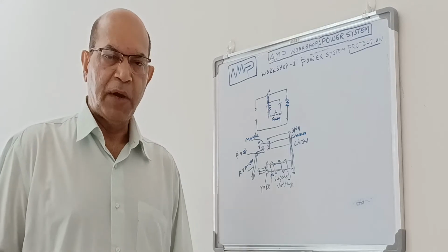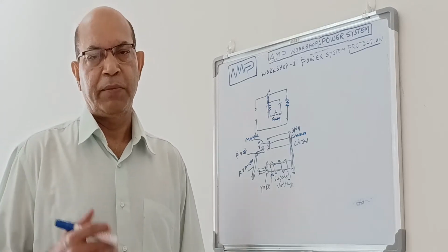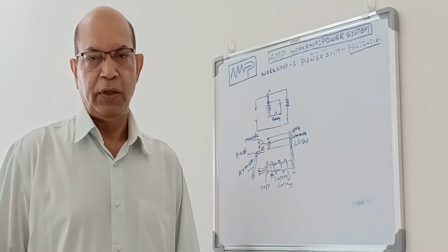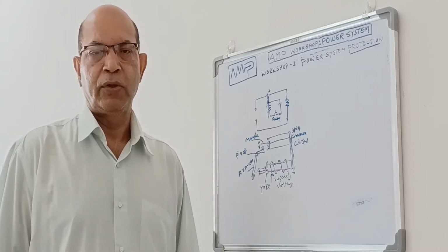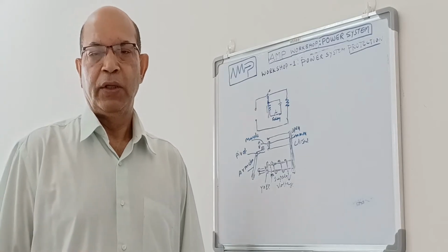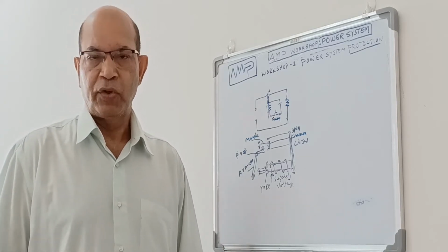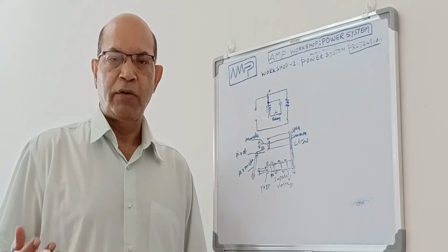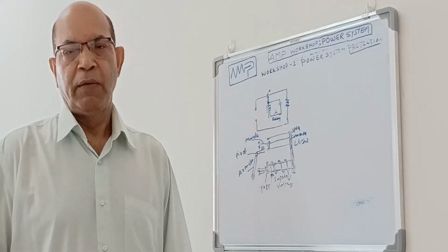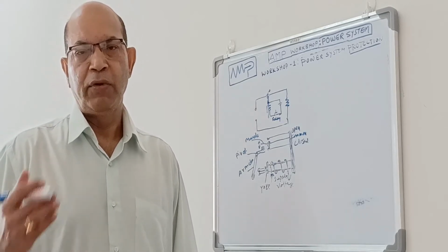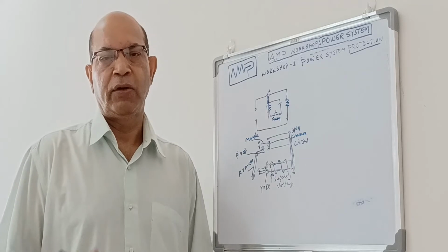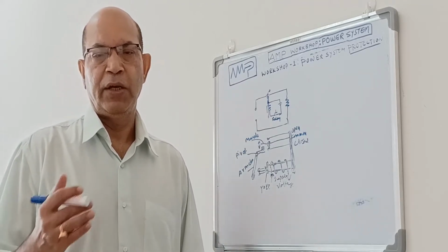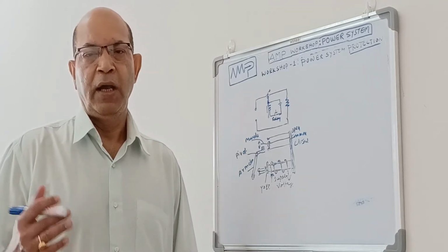By the time of 1985, digital technology came into the picture and the microprocessor was developed. From 1985 onward, microprocessors were used for various minor controls, like DC motor control, metering, small control applications and process applications. When the microprocessor was combined with a suitable algorithm and interface, a new version of relays came into the picture, called the digital numerical relay, where the microprocessor was the main component with the various input-output interfaces and the algorithm.